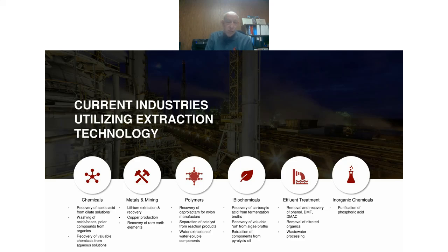And then in the last 15 years or so, biochemicals have become a huge business for not only us, but a lot of people. So people try to make chemicals by natural processes, maybe a fermentation process, an algae process. And oftentimes those broths then have high boiling chemicals in them that you're trying to recover. And again, liquid extraction is a good tool to use in those processes. Certainly, effluent treatment has always been a good area for liquid extraction, because if you got wastewater that has chemicals in it that you got to remove, and they're higher boiling than water, then again, the way to do that oftentimes is by liquid extraction.